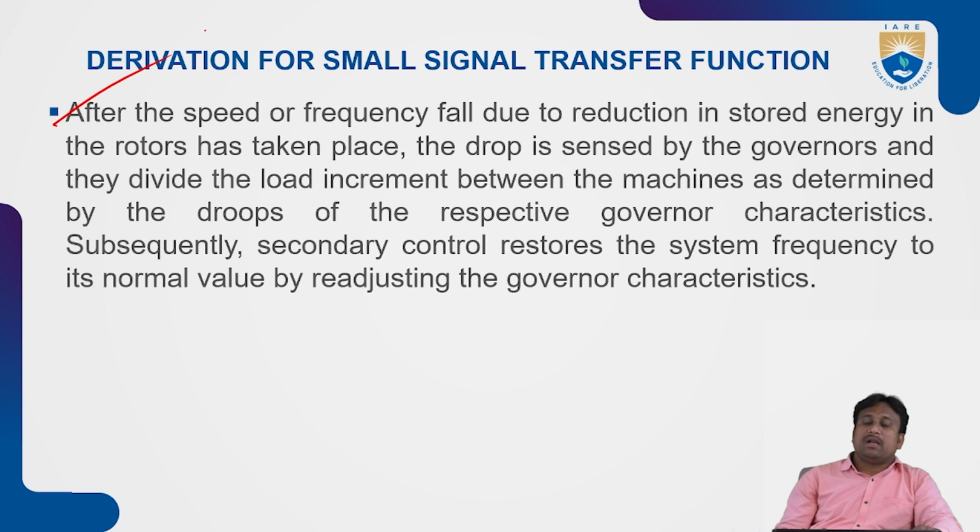So after the speed or frequency falls, due to reduction in stored energy in the rotors, the drop is sensed by the governors, and they divide the load increment between the machines. These are determined by the governor characteristics, according to the respective governor characteristics.